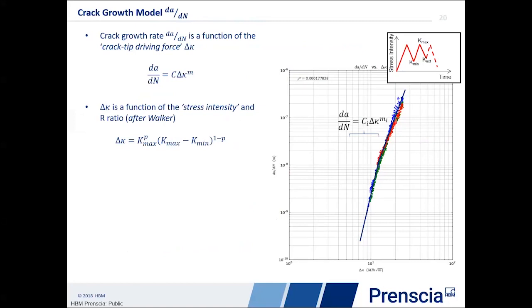So what I have is a parameter, stress intensity max, that's looking at the peak value, and now I have it multiplied by a stress intensity range, max minus min. Smith-Watson-Topper is basically just a subset of Walker where the p-values are both 1/2.